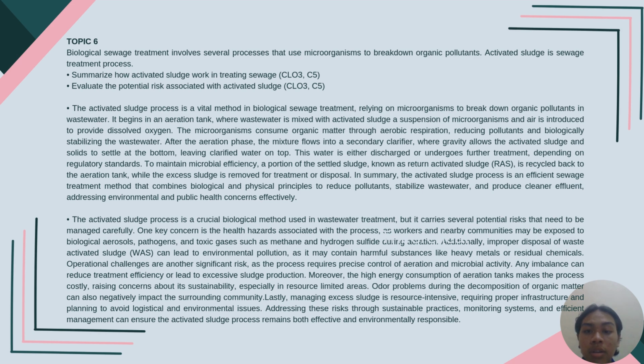Operational challenges are other significant risks, as the process requires precise control of aeration and microbial activities. Any imbalance can reduce treatment efficiency or lead to excess sludge production. Moreover, the high energy consumption of the aeration tank makes the process costly, raising concern about its sustainability, especially in resource-limited areas. Odor problems during the decomposition of organic matter can also negatively impact the surrounding communities.